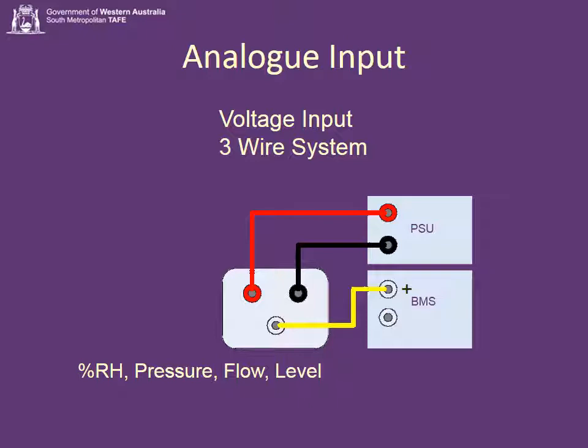Then we have to connect the output of the sensor to the input of the BMS. And we connect that just to the plus side. So just one connection to the BMS on the plus. The minus side, sorry, is typically already connected to 0. So that's all good.